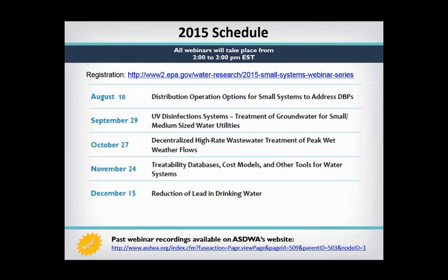If those are existing long-term contamination sources, then anything changing the basic surface characteristics, oxidation reduction potential changes, can certainly mobilize surface deposits and change the solubility of those metals. I think it's when those are on the pipe surfaces that needs to be part of the overall evaluation.